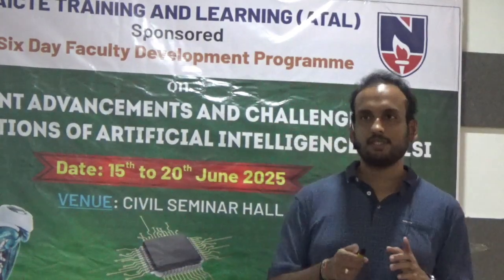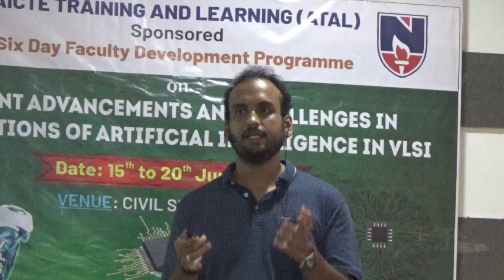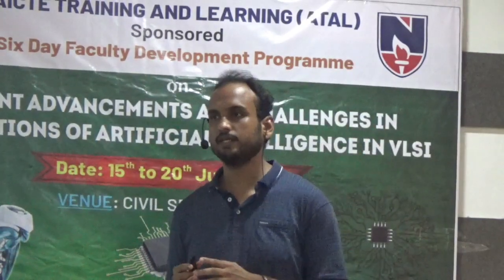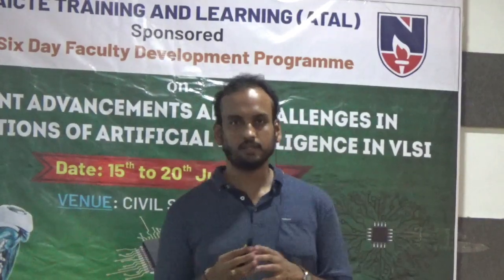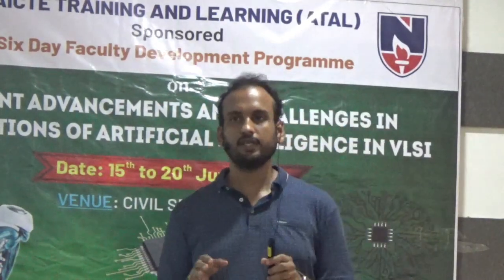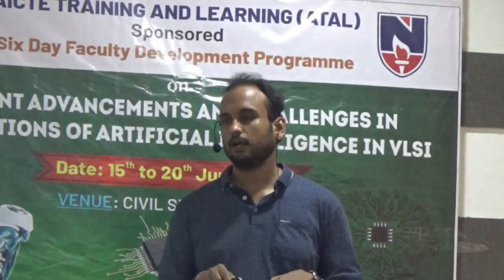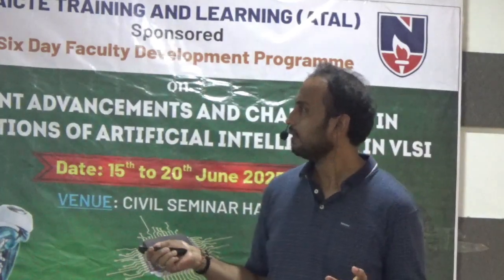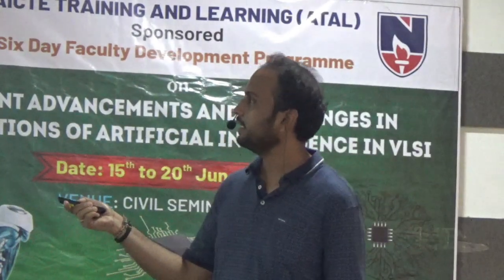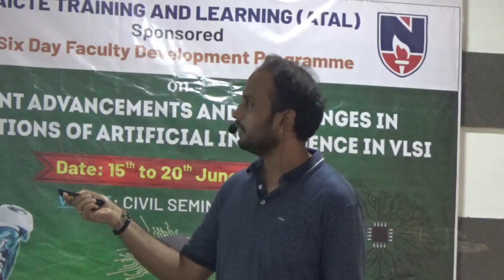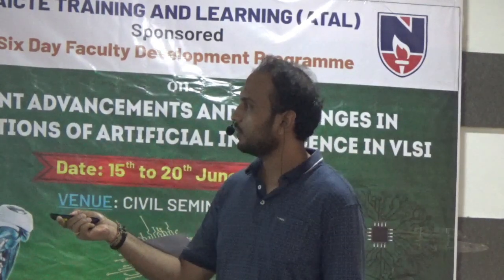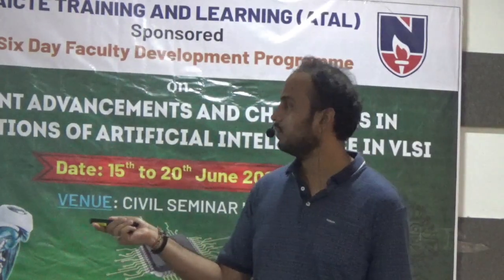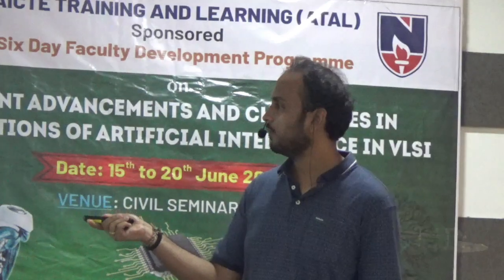So apart from what we discussed about AI and the trends we are seeing in the semiconductor industry, one important thing we are going to see is packaging or 3D integration. Right now we are using different packagings, but going forward, we are more concerned about 3D packaging and 3D IC designs. So this is how different 3D system in package, system in SoC, IC design work, and this is how the interconnects are. Between the two ICs, we need some interconnects. This is how the interconnect scaling happens over the time period.